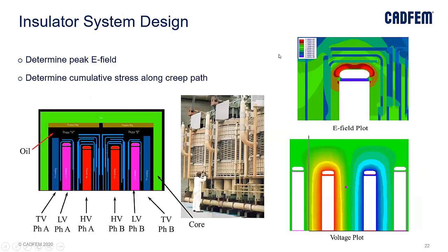Yes, sir. So that is about the short circuit forces, and there is another important aspect: the insulation and the material designing for this kind of transformers, whether it is a power transformer or a distribution transformer. This insulation also plays a crucial role because it will avoid the misfire of these windings or the short circuits. All of these things will create a lot of impact on the performance of the machine.